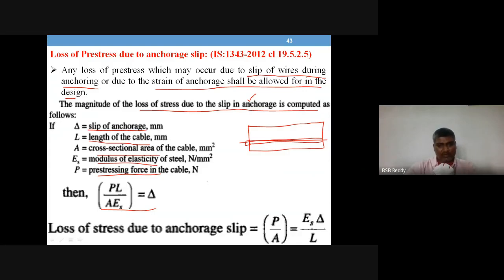So it is simply like delta is equal to PL by AE, which is a well-known formula for axial strain to calculate axial deformation. It is from a very simple basic concept like Young's modulus is stress by strain, where we replace stress with P by A, and strain is change in length by original length. Now you can rearrange like E L by A delta. Now what you want is the delta, that is axial deformation. So E comes down, PL by AE is the deformation value.